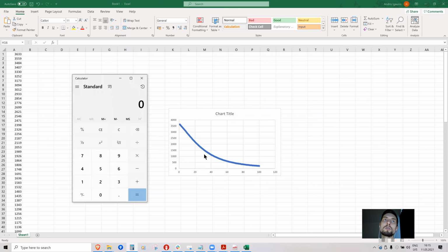This analog to digital converter works at 7 megahertz. It takes the CPU's frequency and divides it by 2, so it's 7 million hertz. But each sample takes 13 of these clocks to finish, because for a successive approximation register analog to digital converter, each bit is 1 tick, and there is plus 1 tick for acquisition. So divided by 13.